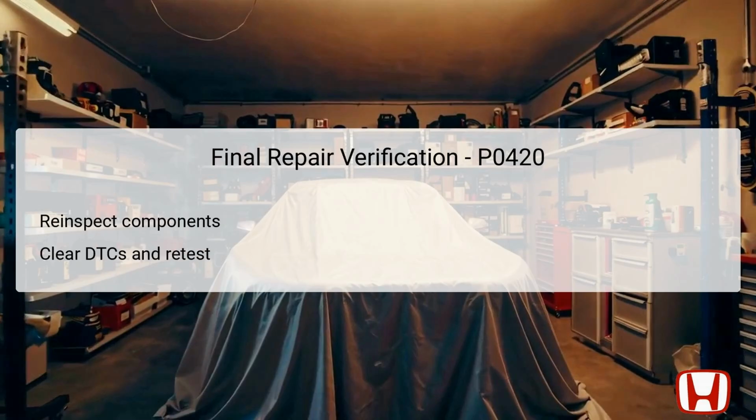After performing the necessary repairs, it is essential to conduct a final repair verification process. This step begins with a thorough re-inspection of all related components, particularly those that were replaced or adjusted. Ensure that the catalytic converter and associated exhaust components are in optimal condition, as well as verify that the upstream and downstream oxygen sensors are functioning correctly.